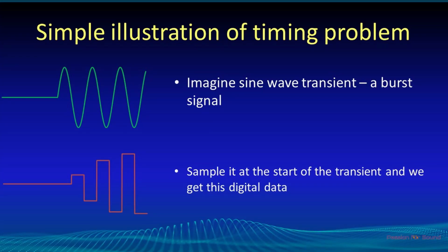The slide that you can see on screen is from one of Rob's presentations explaining his DAC technologies. As you look at the slide, the top sine wave coming in is how the original signal could have been received. The bottom red trace is how the DAC has tried to interpret it using a series of samples. You can see the samples are a little bit behind the actual sine wave, so it's like they're ramping up rather than coming straight in with an accurate representation of that sine wave. That's what they're trying to reconstruct with either interpolation filters or Rob's specific WTA filters.